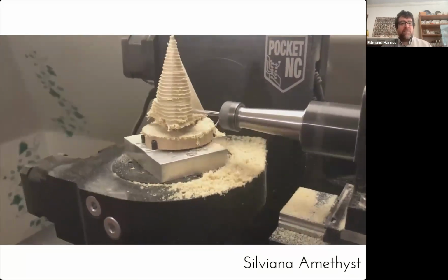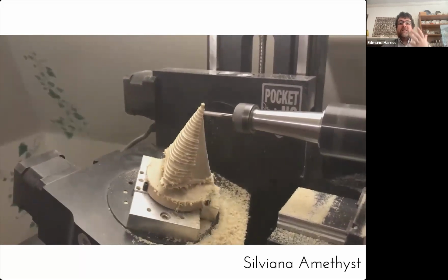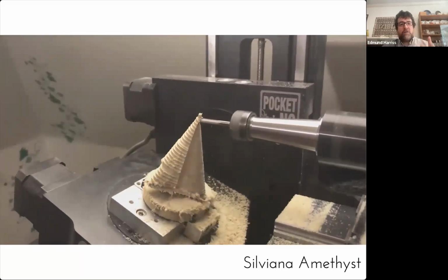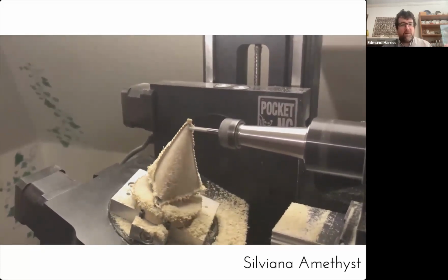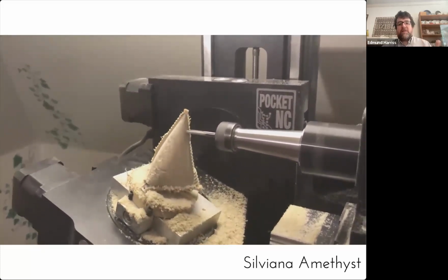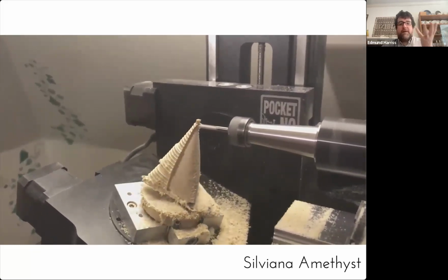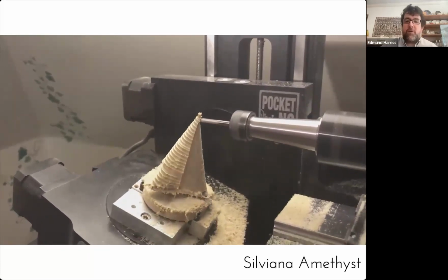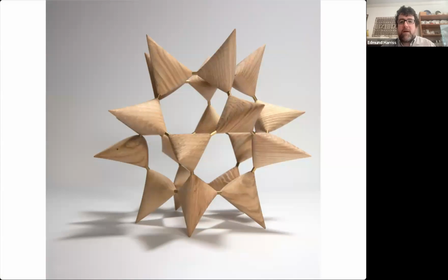You often end up finding interesting ways to make manufacturing more efficient because you're thinking about how you can think about that abstractly. And so, for example, you can get a smooth surface more efficiently with an idea like this, where you're staying on the normal, and so you can cut with a flat end mill. And here is the finished piece.